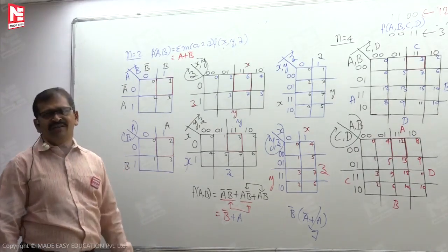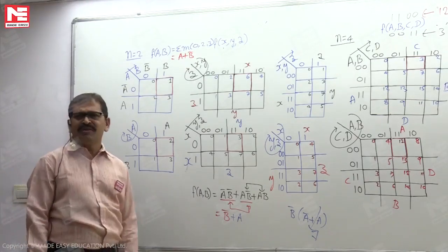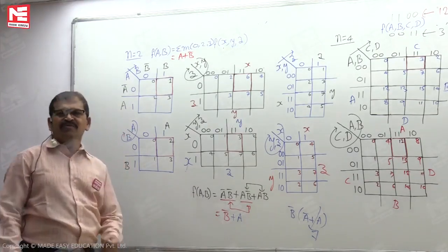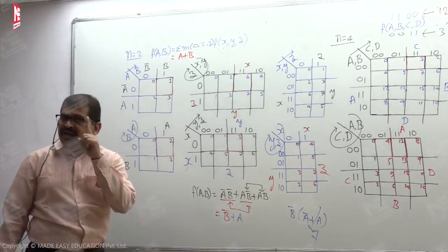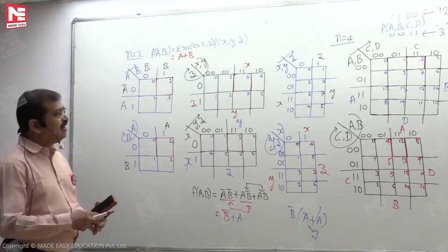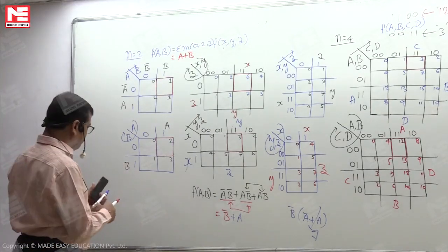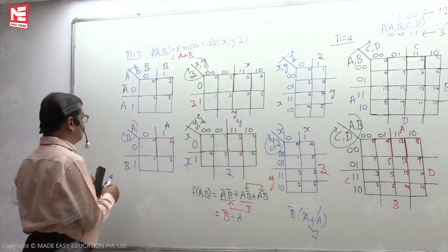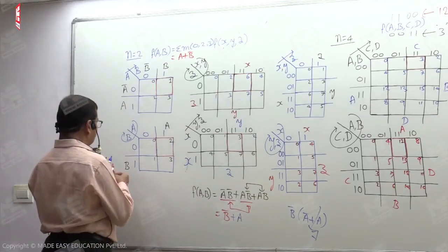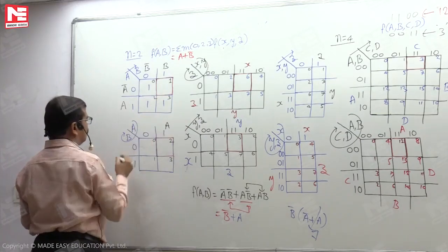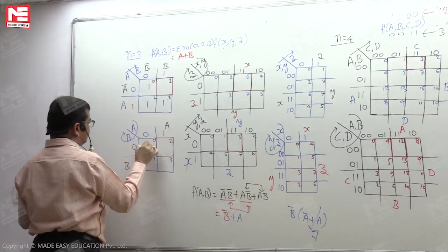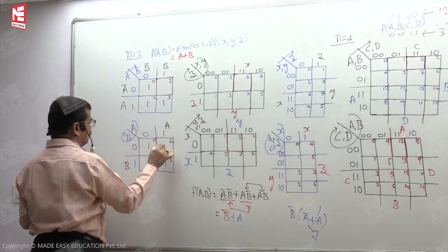So the K-map, we said, is an alternative way of writing a truth table, so that similar work we will have here. Instead of row we use the word cell. So in the cells 0, 2 and 3, we must write the function output as 1.